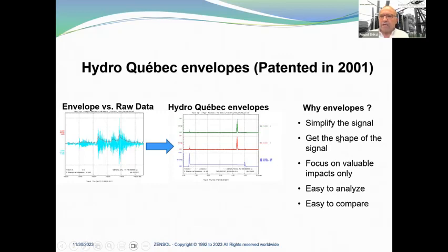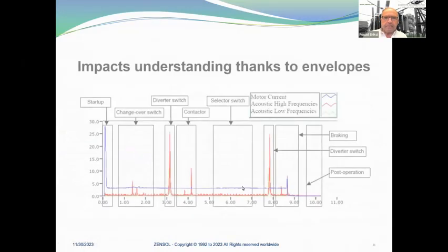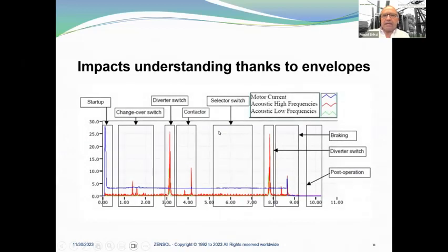So now, why envelopes? Because it simplifies the signal, it gets the shape of the signal, we focus on valuable impacts only, it's easy to analyze, easy to compare. And thanks to the envelope, we understand the impacts. Typically this is our challenge, to understand these signals.